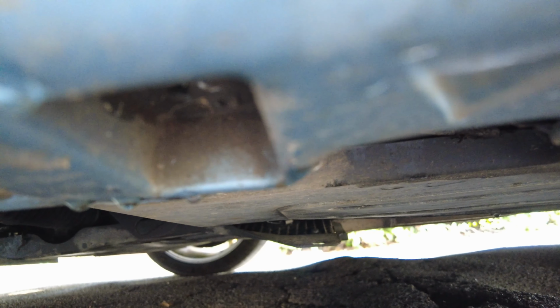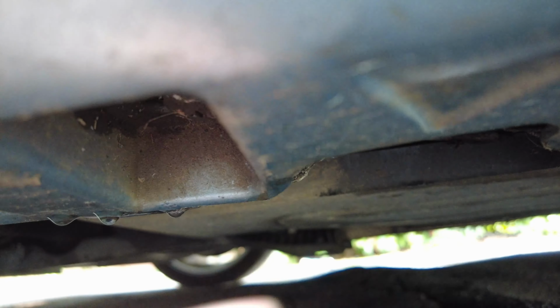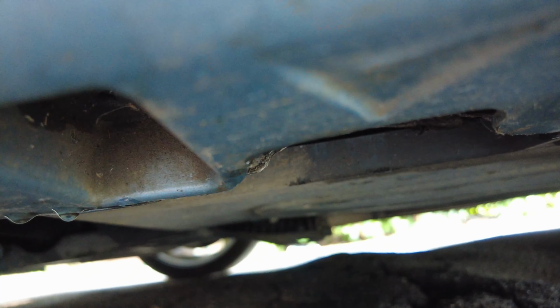This seam should be behind this seal cover. It's not. You can see it's been deformed, and it's deformed the seal. Fortunately, it's not too obvious, so it's merely a cosmetic thing. If we pop round to the other side, you can see what it should look like. Okay, so this is the near side front, or the passenger side in the UK. Again, here is the indicator for the jacking point, and just tucked behind here is the seal. The puck goes over there, and then you're able to jack up.